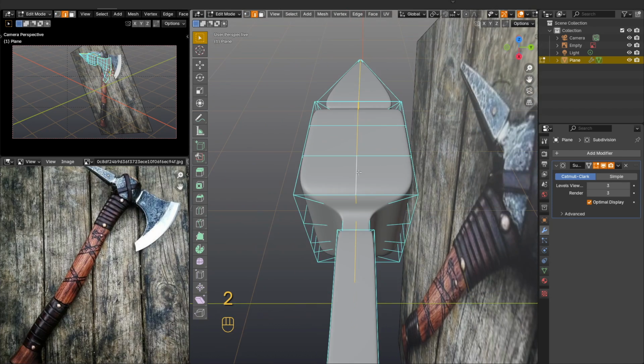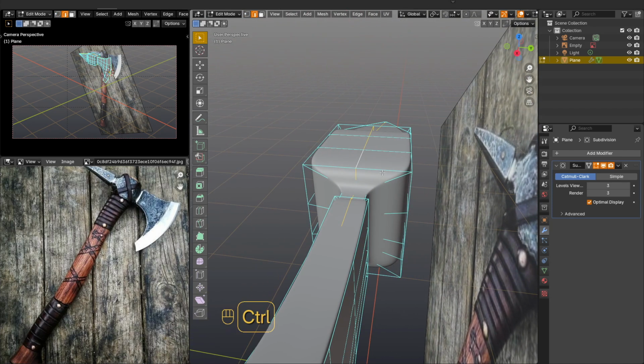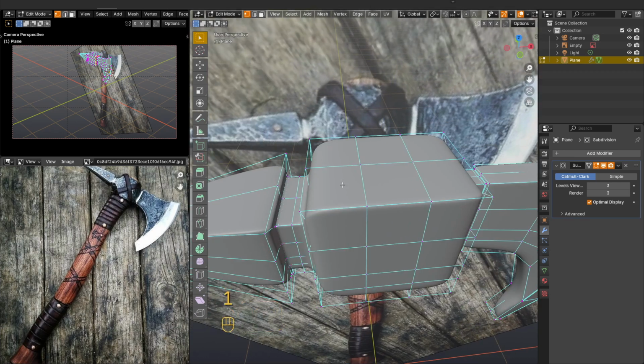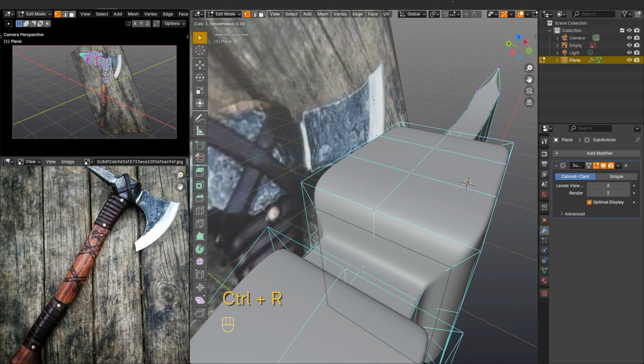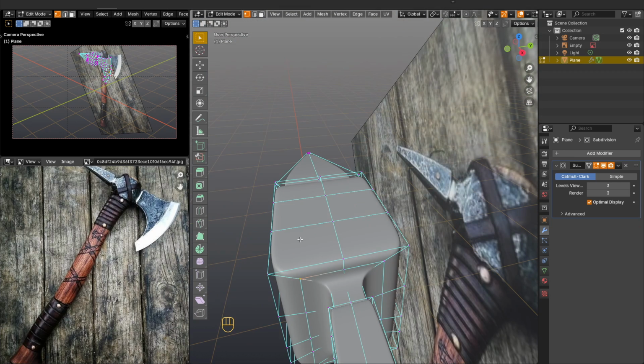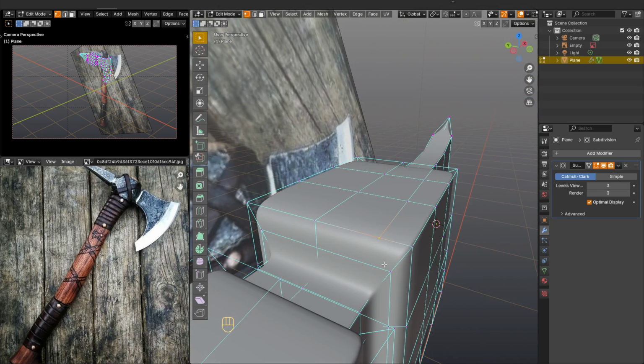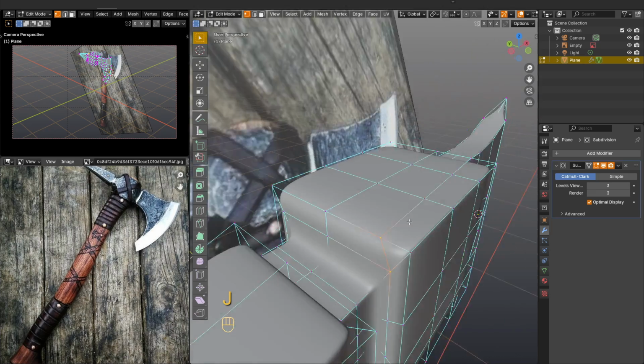Now I want to make a hole for the handle in the central part. For this you need to make at least 9 vertices in the upper and lower planes. Let's add square edge loops on both sides of the central part. And then press the K button on the keyboard and use the knife tool to draw 2 straight lines along the surface so that we can combine the previous 2 edge loops and edges that we will create with the knife tool. After that, select 2 vertices at once and press the J button to combine.